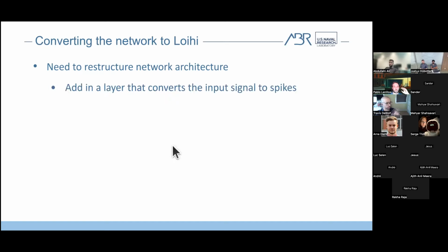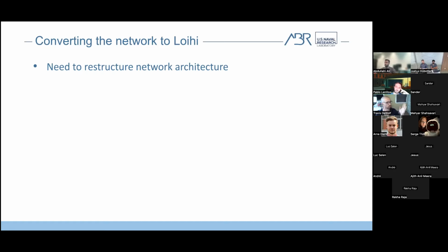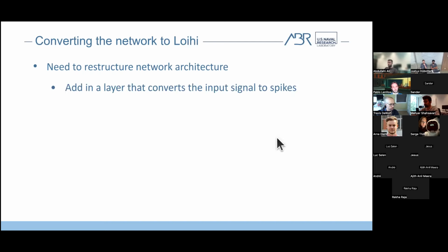And that is just not possible in Loihi 1, to have that many neurons directly connected, like 2 fully connected layers of 20,000 neurons. The max you can have in Loihi is like 4,000 neurons in each layer if you have a fully connected layer, just based on the memory constraints.